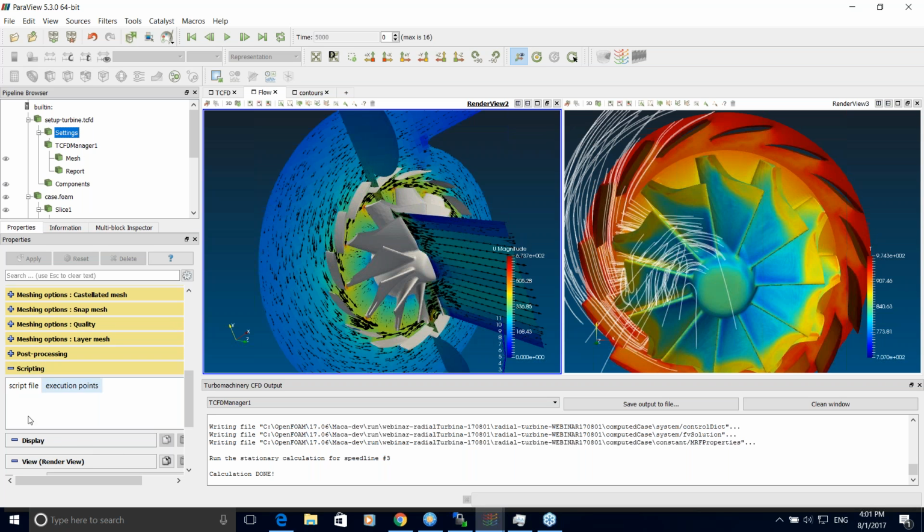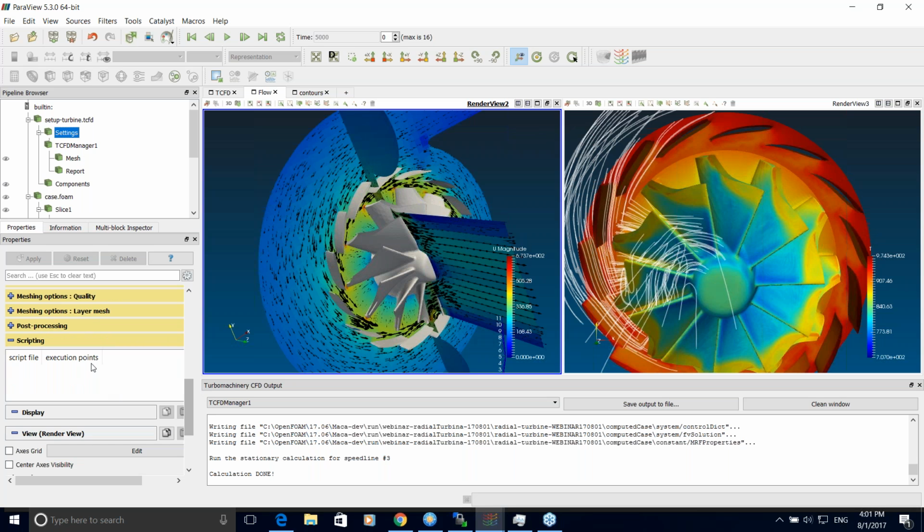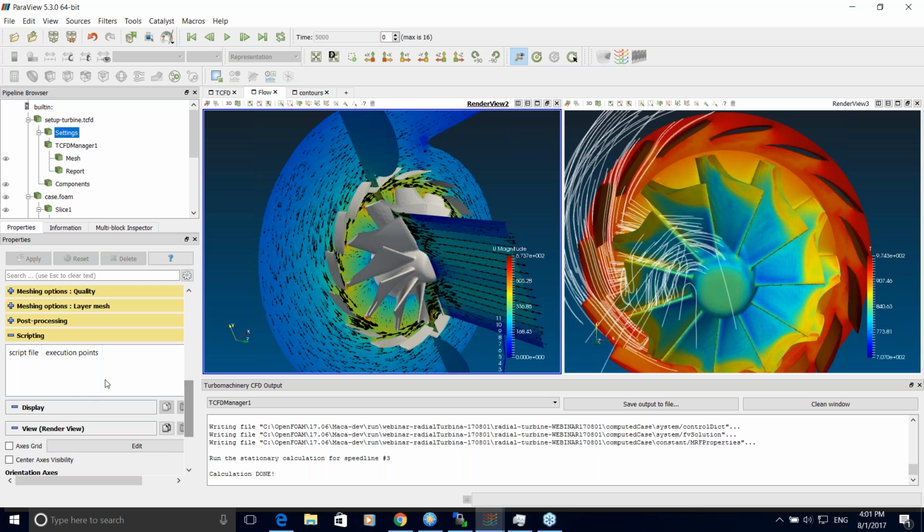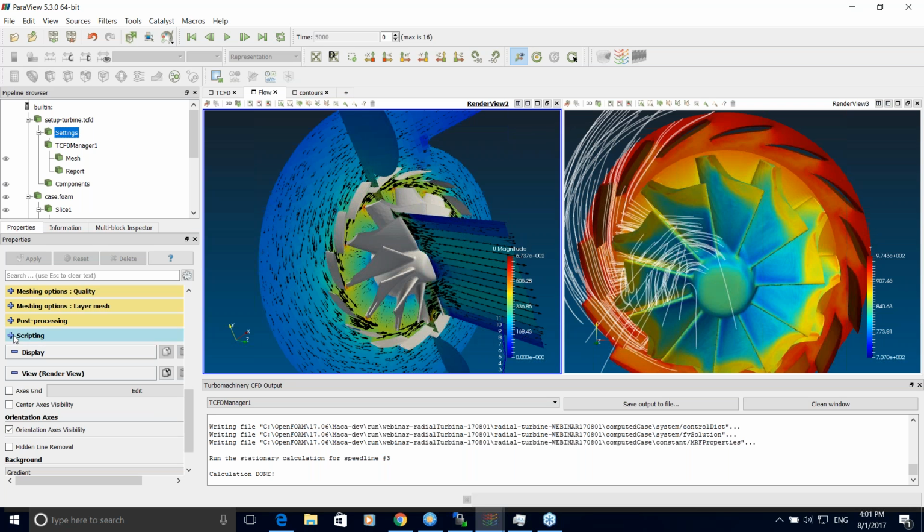scripting module, we are able to prepare the script to set any turbulence model which is implemented in OpenFOAM. So not directly, but it is possible using the scripting, which is a simple Python script which modifies the OpenFOAM case and sets the given turbulence model, which is implemented in OpenFOAM.